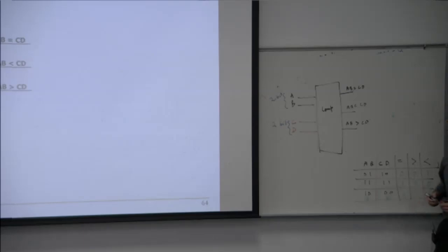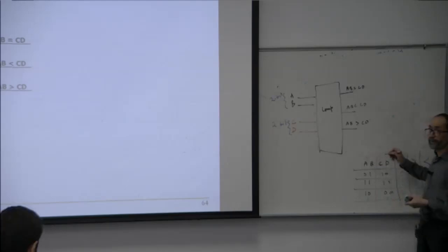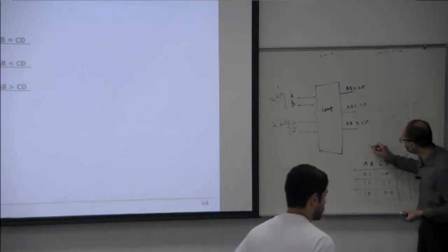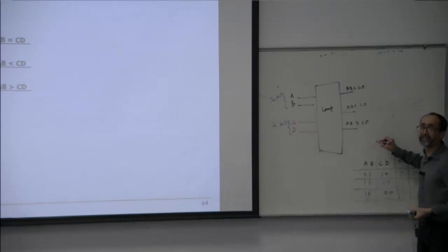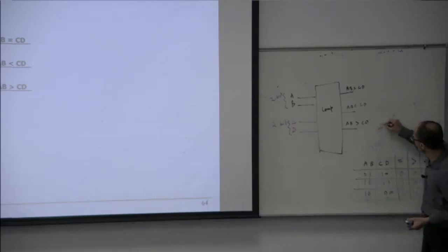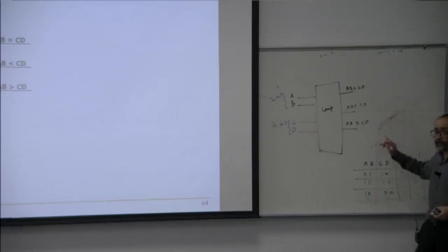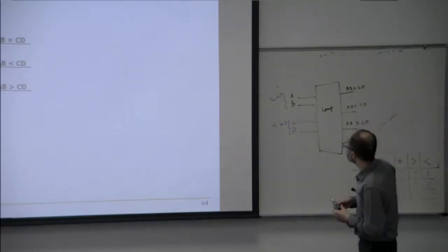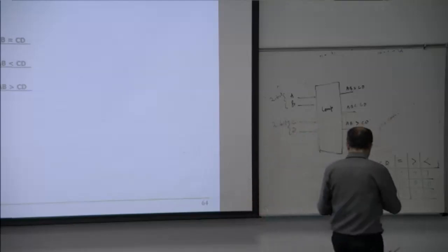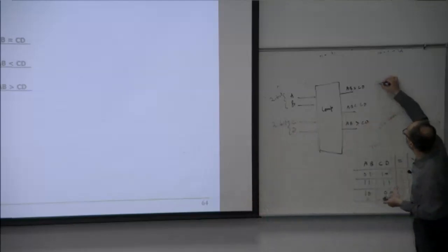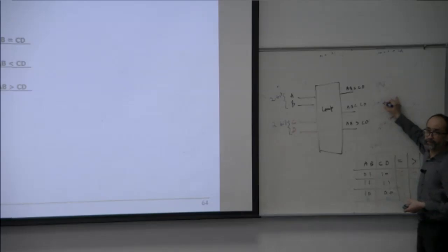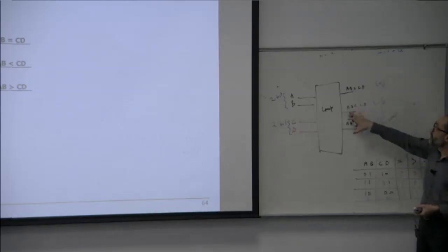So now we go for all of the possible combinations. How many possible combinations for the variables AB and CD? If we combine them, it is 4 bits, so 16 combinations. Now this comparator is computing the equal, EQ, then LS and then GT.